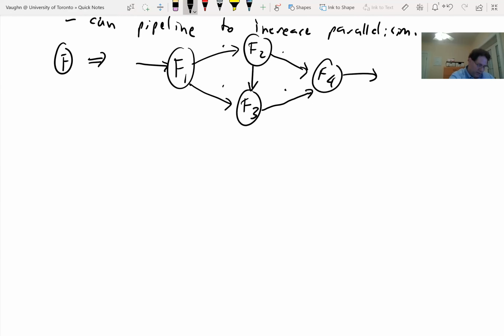So again, we don't have a centralized state. And if we just start putting pipeline registers in there, we keep the data very distributed. So we avoid any bottlenecks where we might be gathering a bunch of data together and then broadcasting it out to a bunch of replicated functional units. So pipelining is a great optimization. Okay, so hopefully I convinced you you want a pipeline, especially in an FPGA. They are very friendly to deep pipelining.